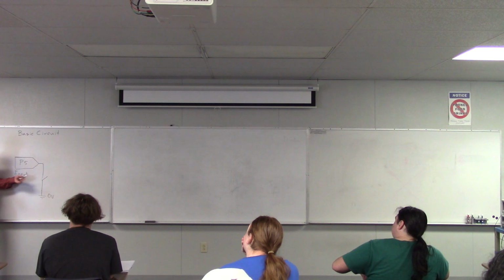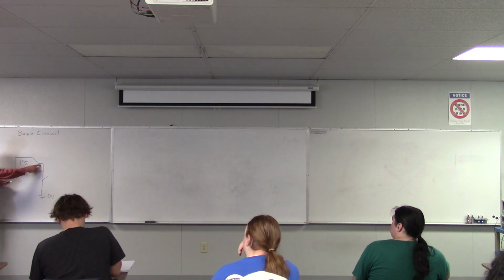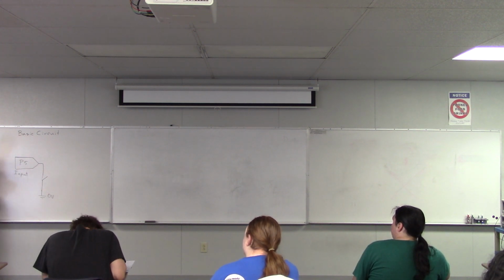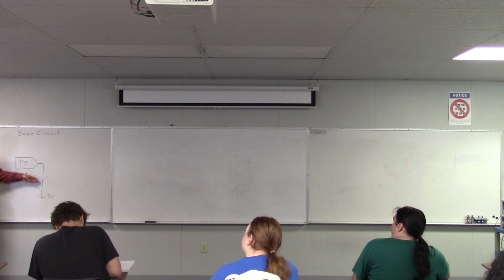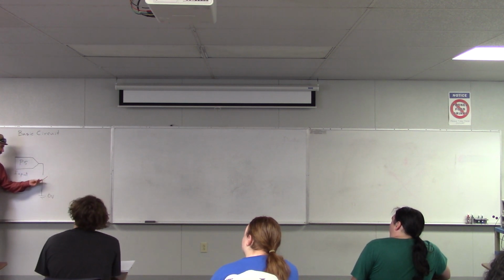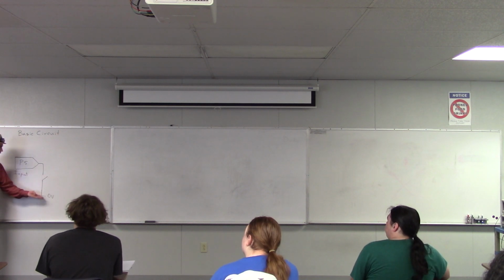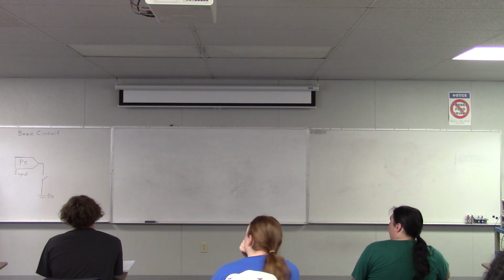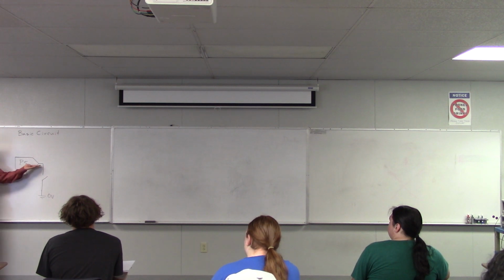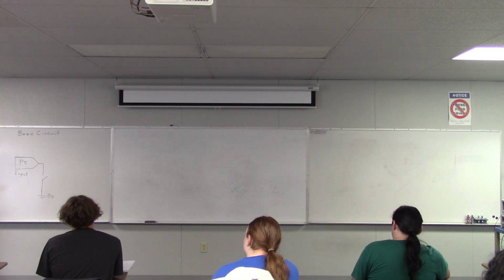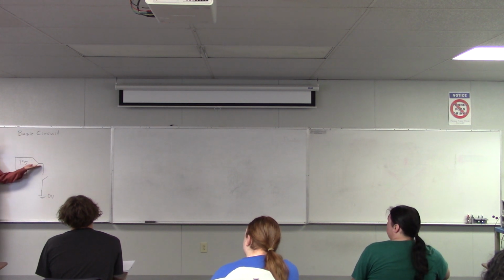So far, when the switch is closed, we have 0 volts here, so that's good. But there's a problem. What voltage do we have at this pin when the switch is open? Is that pin connected to 0 volts? No. Is it connected to 5 volts? No, there's no connection to 5 volts there. So what voltage is that going to be? It's kind of a trick question. Zero? Well, it might be 0.